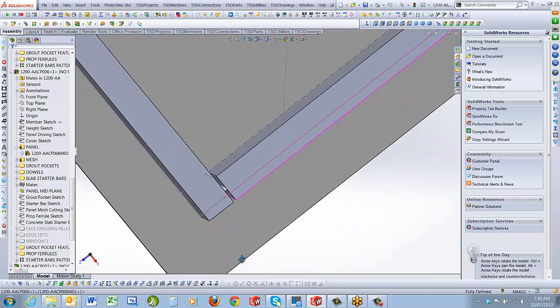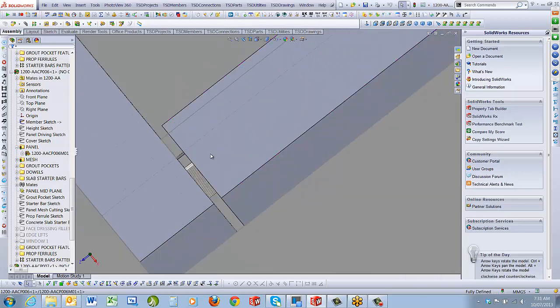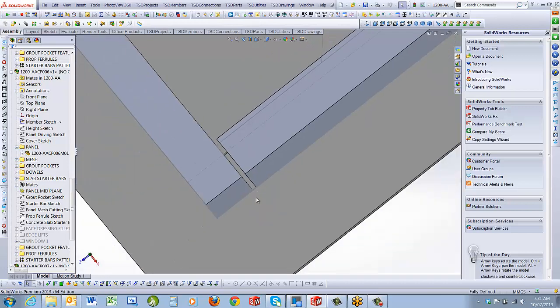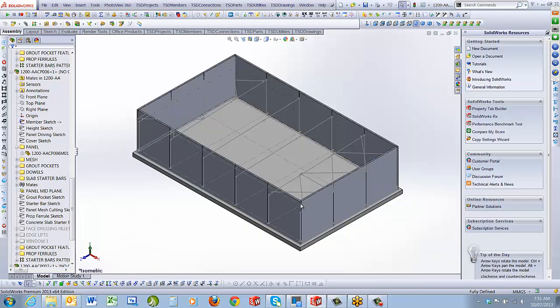And if I look down there, you'll notice the rebar is still sticking out. So I've just done one rebuild, so the next thing I need to do is another rebuild with Control Q, and that'll give a bit more of a deeper level rebuild. And now you can see that the reinforcement's gone. Now I could do that on all the corners. I just wanted to demonstrate that it's pretty quick to actually set that up.